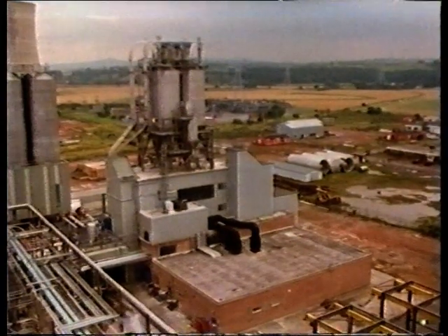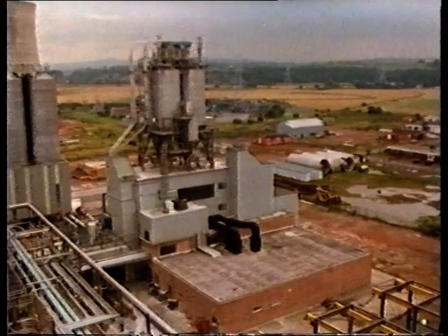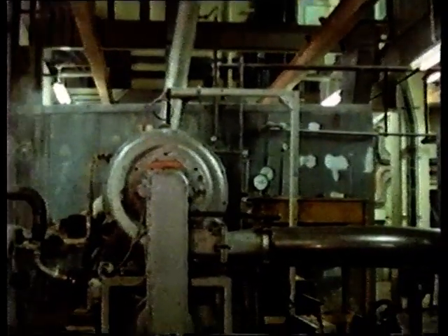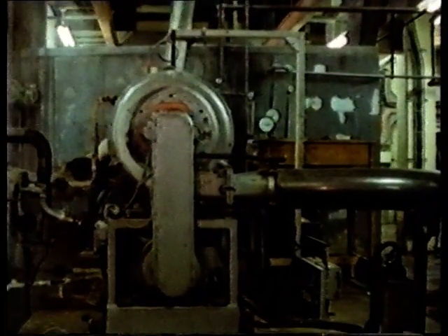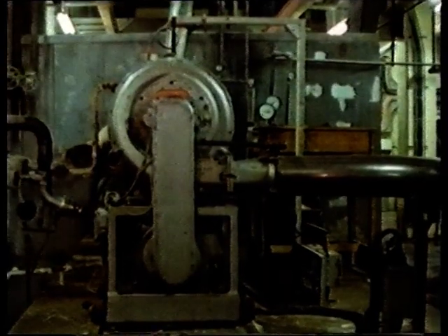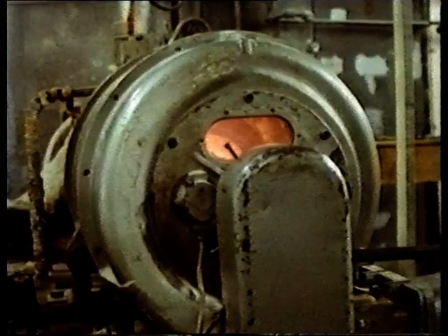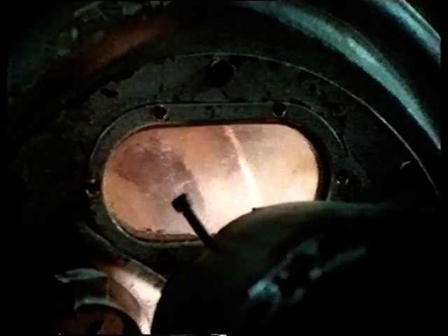In this next part of the process, the white powder is turned into larger pellets of polyethene. Inside this plant, the powder is first heated so that it melts. Polyethene is a thermoplastic which can be softened by heating. In this machine, the melted plastic is forced through holes and it's sliced into little pellets as it emerges by a rapidly revolving metal blade.